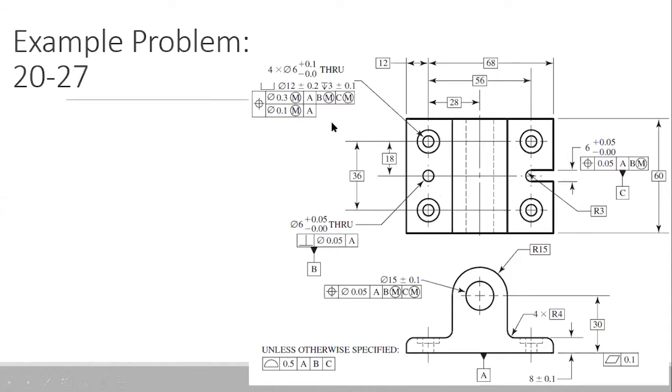These are generally used if we are controlling the orientation of all the different holes together. We are not going through that level of description at this point of time. But if you are interested, you can always reference the text on the position control of a group of holes. How can we control the position of a group of holes? The 2 levels of this feature reference frame represent that.